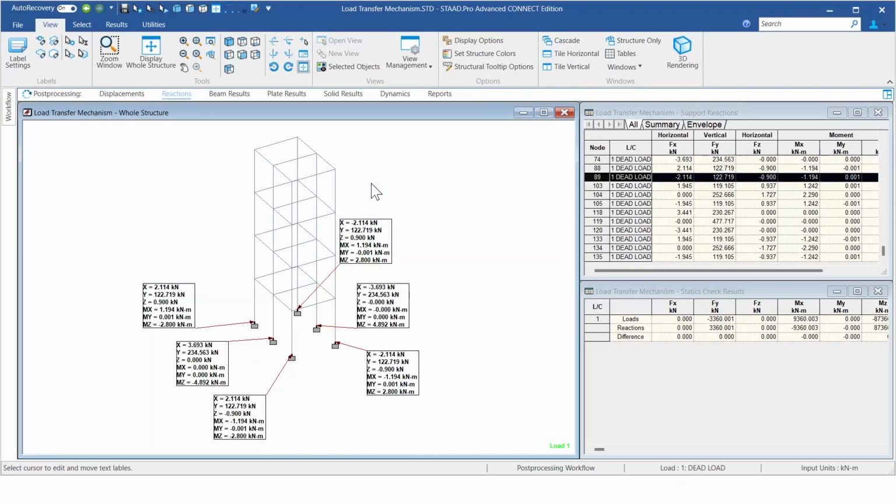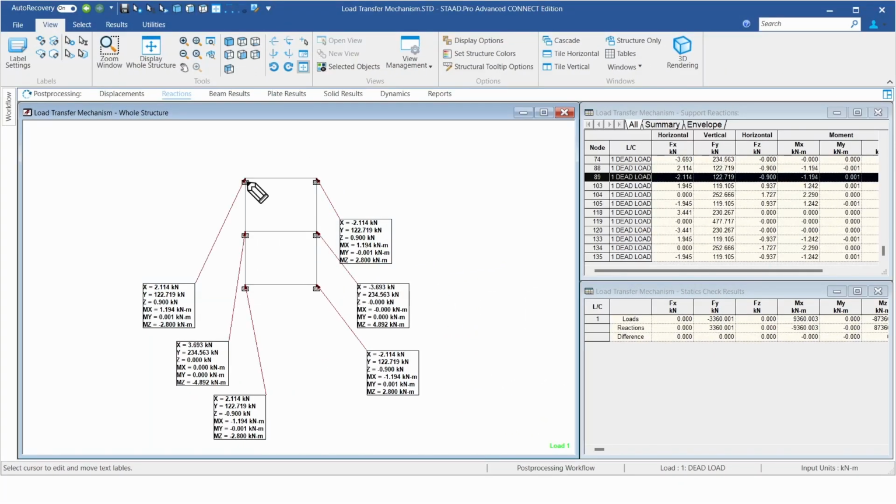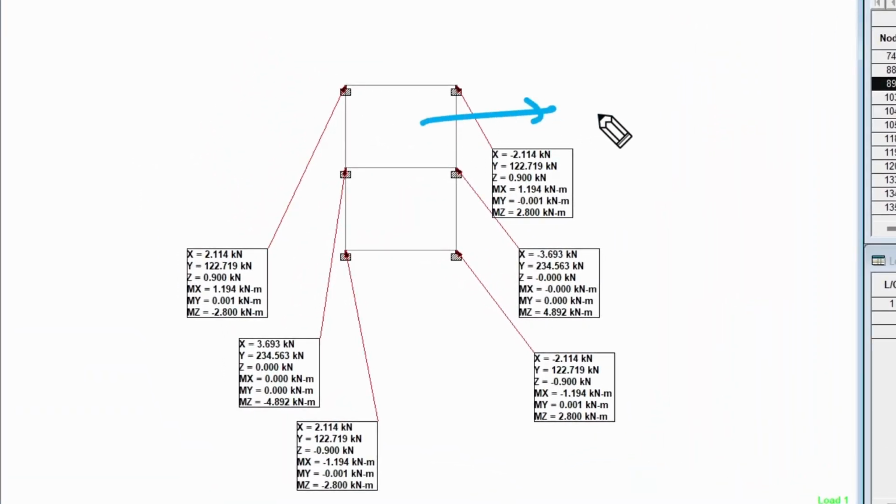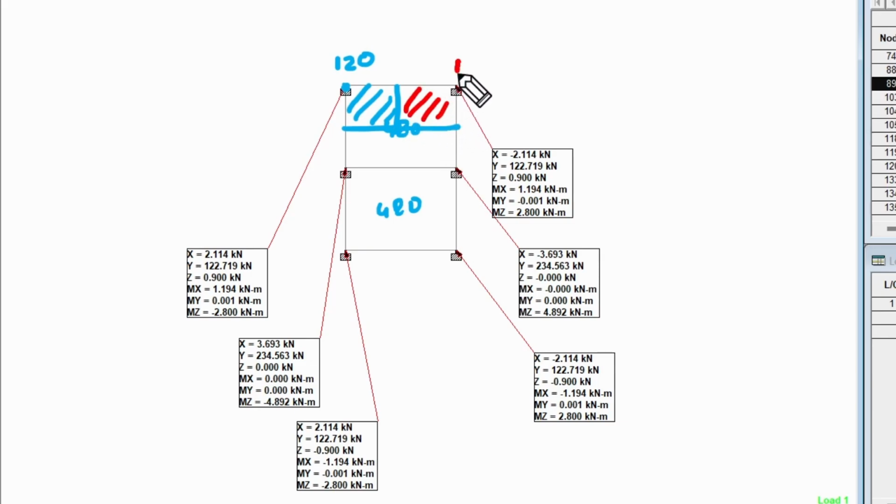That is, if I go to the top view. If I were to talk about the floor load, this floor load was 120 multiplied by 4, that was 480. That is the floor load right here. This is 480 and this is 480. This node right here is taking 1/4 of this entire 480, that is 120. That is well and good. This floor right here is taking again 1/4 of this, that is again 120. That is also good enough.